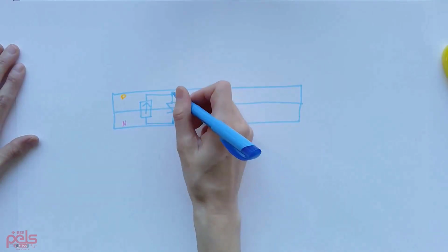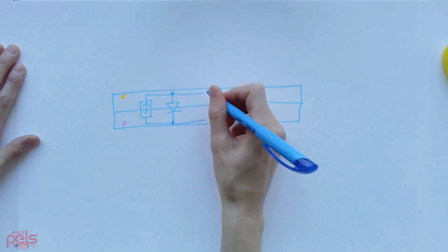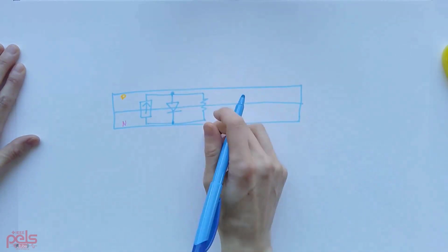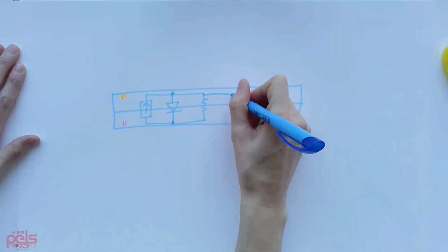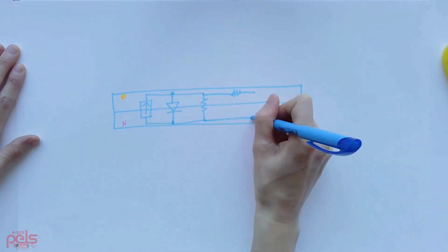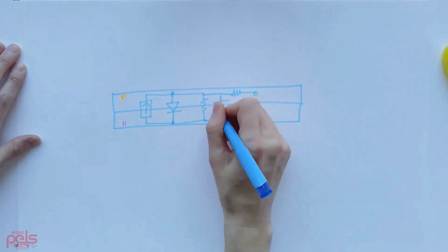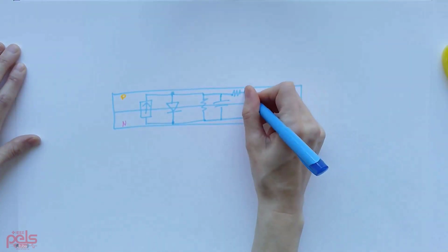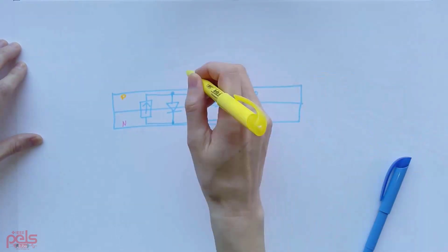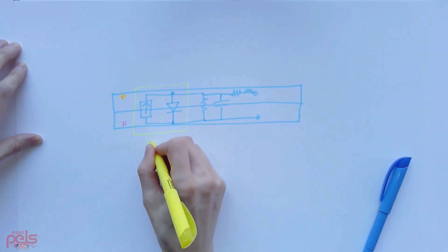I will mention that there are actually some other things going on in this circuit. There's going to be some resistance between the P and the N, positive and negative terminal. There's also going to be some resistance that happens coming out of the circuit. And if we want to get into the advanced modeling, we'll also have some capacitance and some inductance at the end as well. So this is our advanced model, but we are just going to focus on this ideal model. So this is the ideal model for the PV.